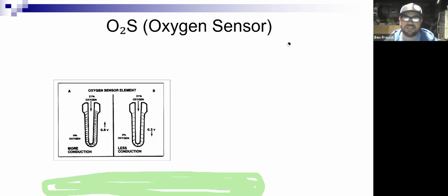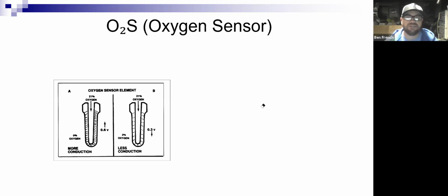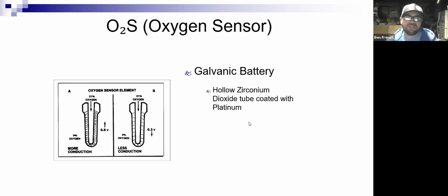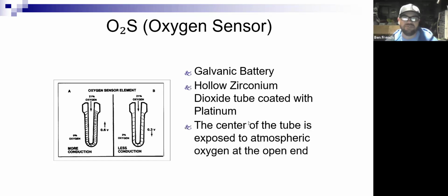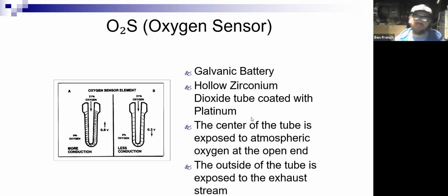So this gets us on the tangent of, well, how's that O2 sensor work? If he's important for this closed loop thing, what's going on with him? We're not going to get into all the theory of the different O2 sensors. There's zirconia sensors, there's titanium. We're not going to go into all of that, but we are going to get through some of the basics. What this will do is make it a little bit easier to understand when you get to engine performance, or if you've already had it, it's a good review. Most O2 sensors are zirconium. So that's what I'm using for my example here.